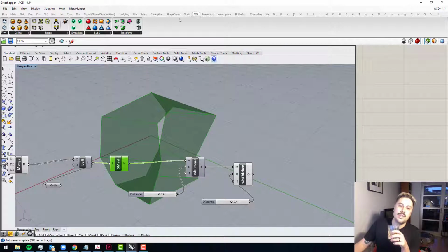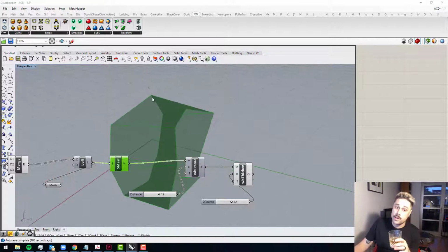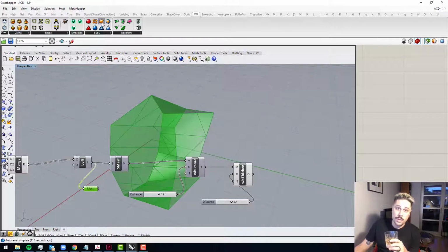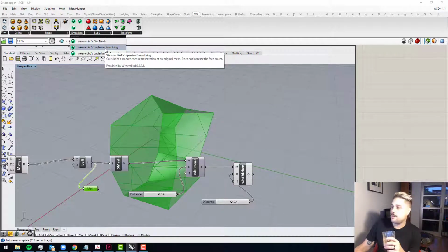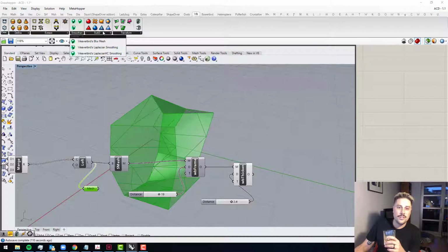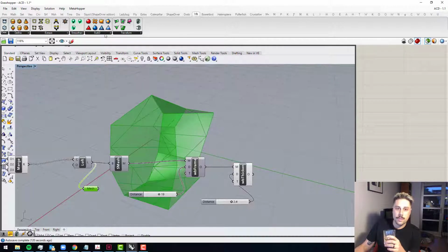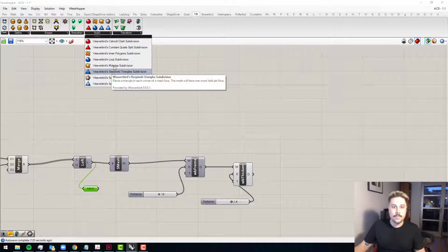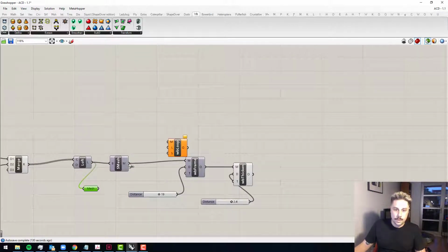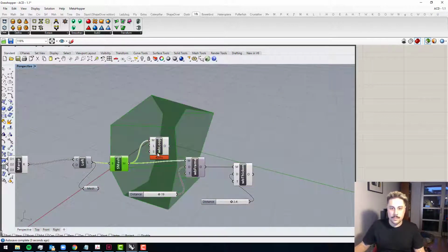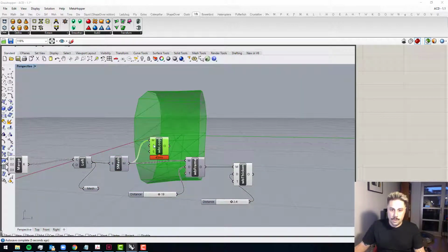So we're gonna subdivide these faces, so not by a million like the way that Rhino did in here. Not a million, but you get what I mean. But let's smooth it off. Usually, my go-to one is loop subdivision. Where'd it go? Oh, maybe because I've got that turned on, I won't like it. There we go. So, loop subdivision. There we go. You see it, what will it do?